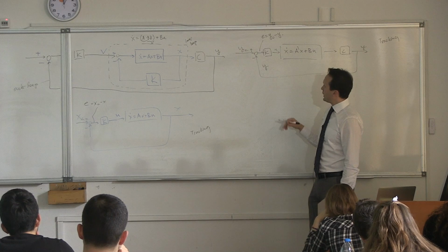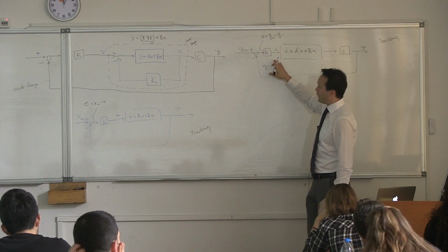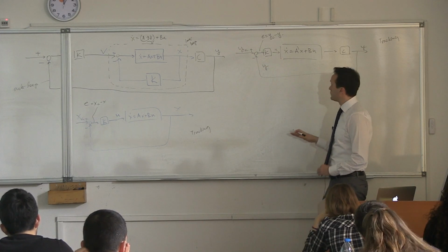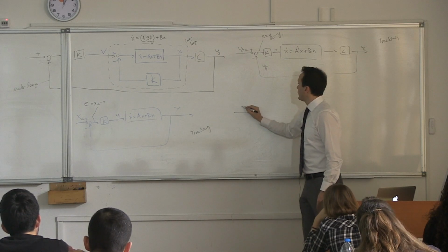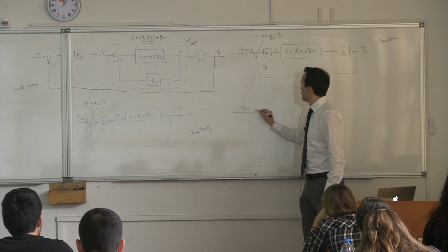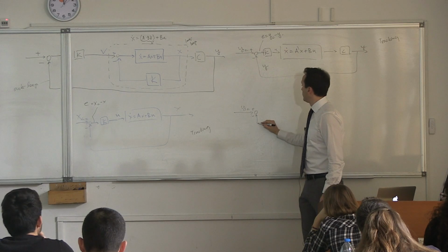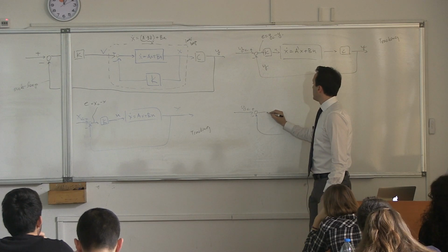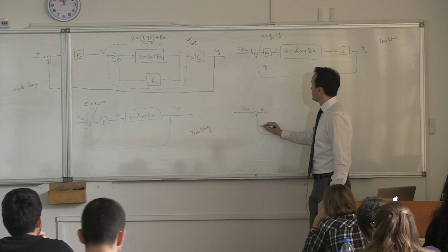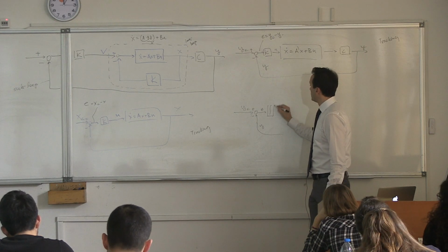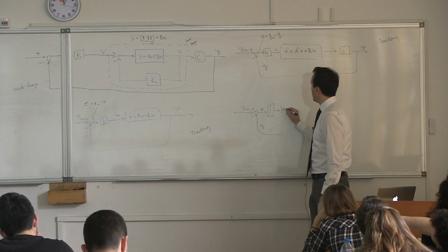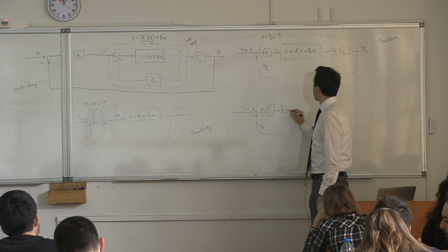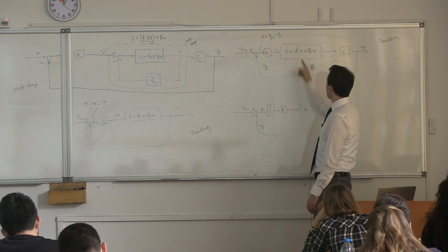So we had a similar architecture for this. We called this the integral controller, right? So it would look like this. We had a command plus minus, and then we took the error, took the integral, multiplied it with a k, and then sent it to this.